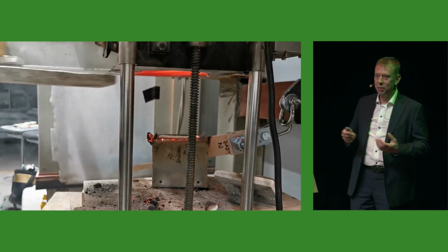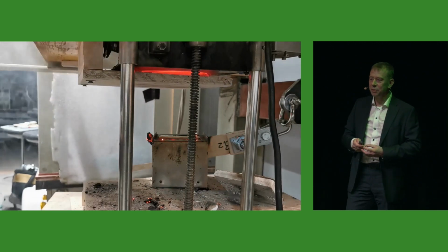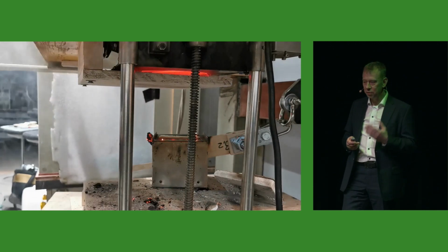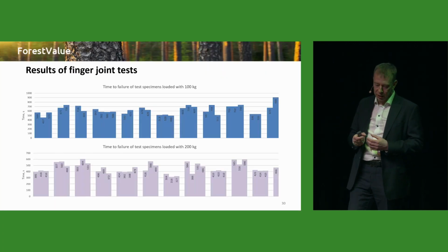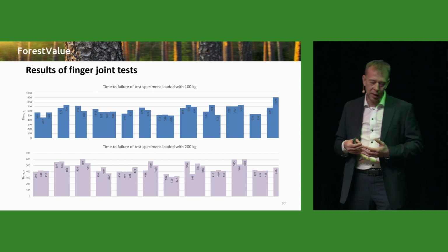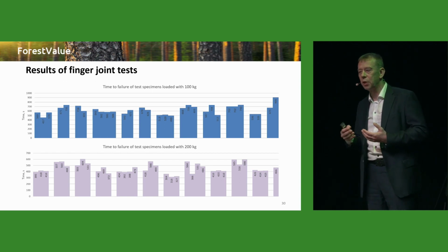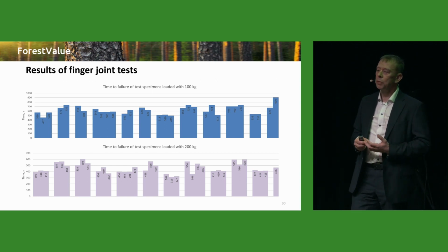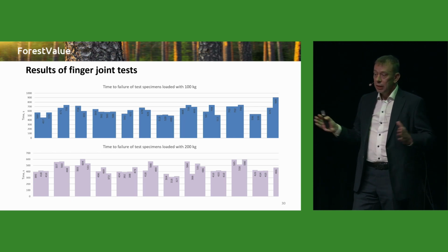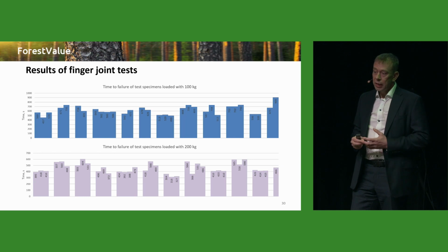That's fun for us always, to break something, to burn something. So this was now the time to failure moment. And then we observed the failure mode, whether it was adhesive failure, wood failure, or mixed, and what the charring mode was. That's also very important.